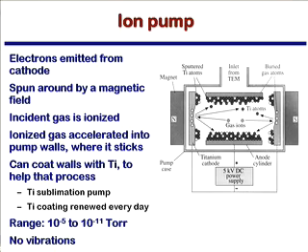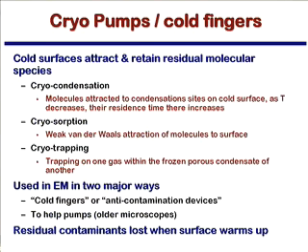Now, if you start adding a bunch of turbo pumps and a bunch of ion pumps onto your machine, it gets expensive. That's one of the reasons that the modern microscopes are increasingly expensive. If you're doing something like a field emission source, you have to have very good vacuum. You put a number of ion pumps up near the source, and it adds up with time. Okay, so it's one of the things that makes these things cost a fair amount.